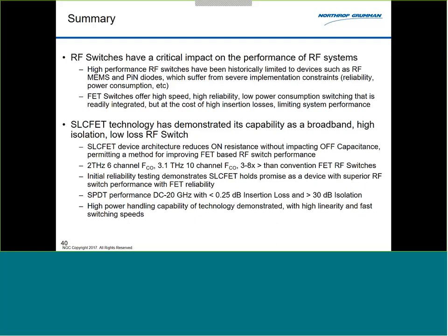But the off-state resistance is very important. For the device to work properly as an RF device, very similar to a power device, you need to have at least six orders of magnitude between what that off-state current is. If that off-state current starts creeping up between the source and the drain, your RF performance also goes to the tank.